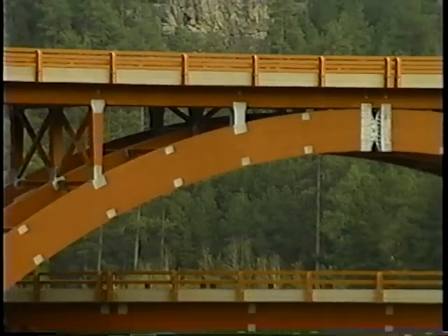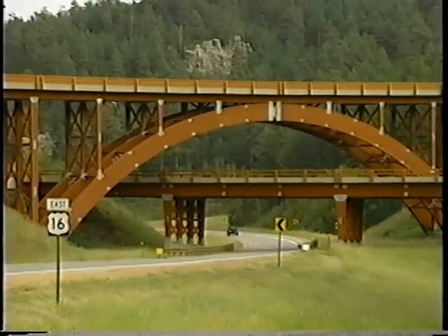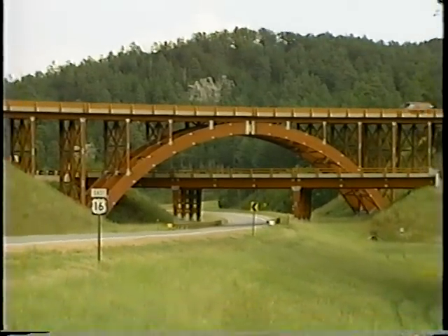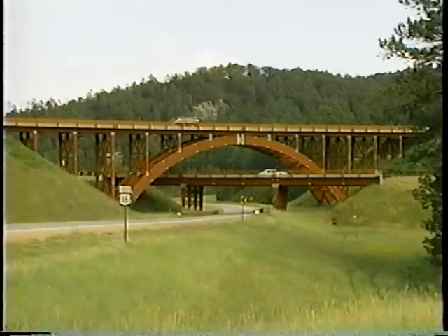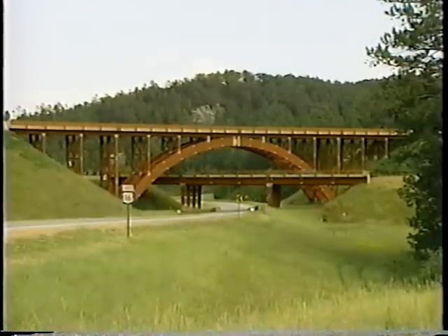Requiring full-scale crash tests for all new bridge railing designs was not the only change in the AASHTO guide specifications. Because bridges in different areas carry different kinds and volumes of traffic, the AASHTO guidelines contain 3 performance levels to suit conditions at different bridges.